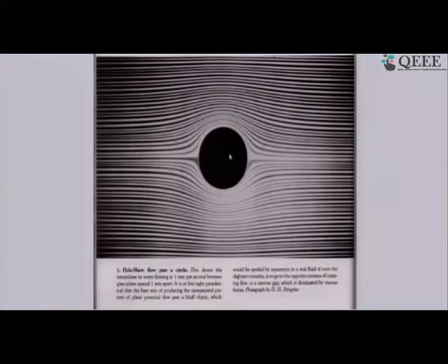So if you draw a vertical line over there, the left and the right of this look almost like mirror images of one another. And that's what happens at very, very low Reynolds number. The second thing we see here is that this streamline is going like this. It is bending very little and then recovering back again. What it means is that the flow between this streamline and this streamline, as it came over the cylinder, was squeezed in this much only. So the flow accelerated along this path, and then again it decelerated to recover its original velocity.